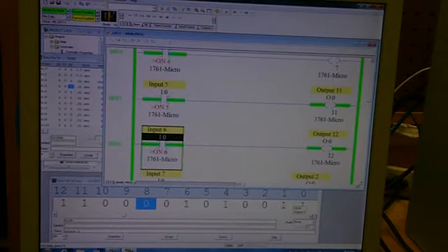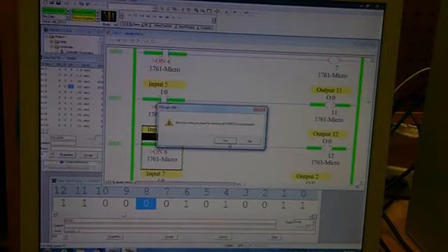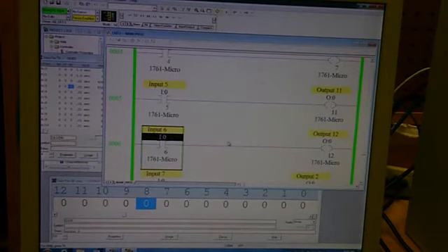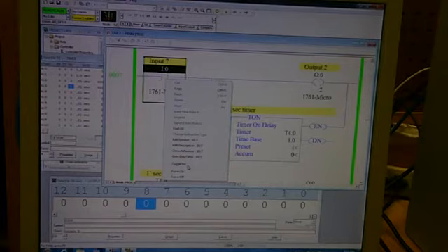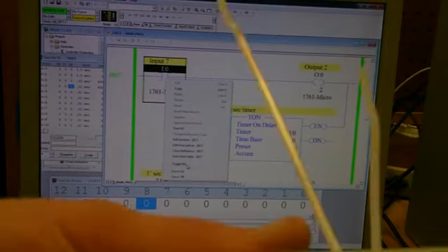Okay, now up on top here, I'm going to remove all my forces so I don't have to go back and do it individually. So I've removed all my forces. Now I'm going to turn on 7, and when I do that, we're going to see our timer working. Are we ready? Okay, so the 2's on. Second 5 later, the 5's on. 7 seconds later, 7. 4 seconds later, the 3.